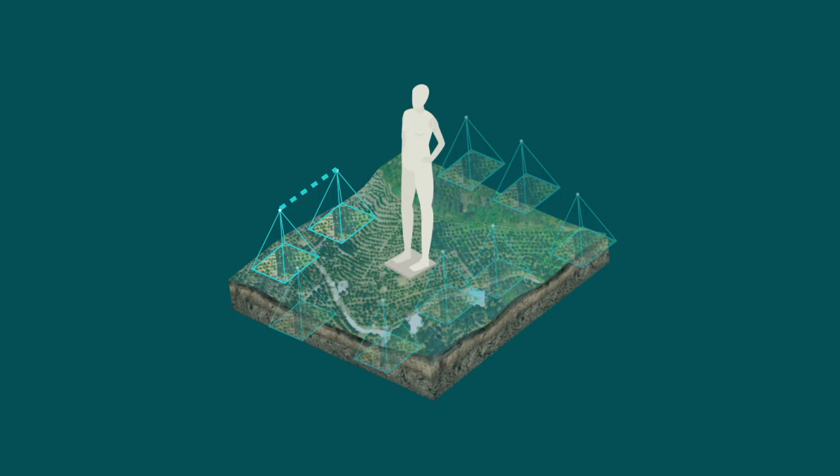And if the resolution of the data that you've captured is such that those 2 points are captured at a resolution of a meter, basically you cannot have centimeter level accurate measurements. That's quite intuitive because those 2 points are within the same pixel almost, so to speak, in the drone's data. You cannot expect to get centimeter level accurate measurements when those 2 points are essentially the same point when it comes to the capture.